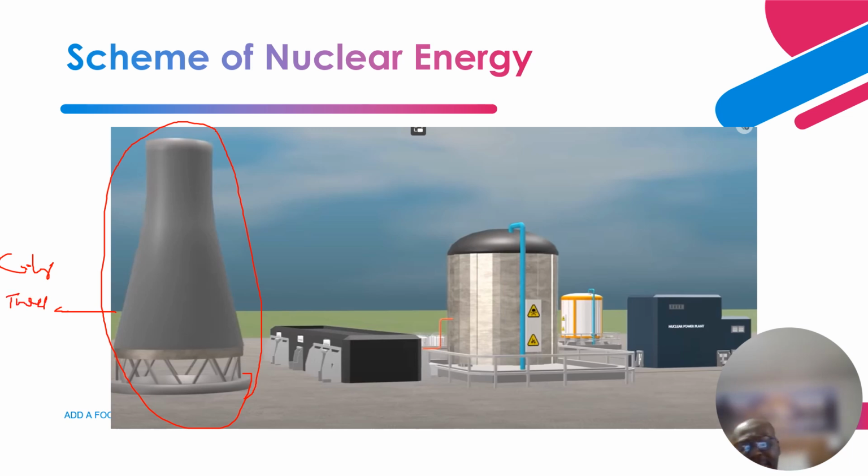This one acts like a heat exchanger, that allows the wasted coolant water that comes out of the condenser to be cooled utilizing river source water, and it returns back into the loop as a closed cycle loop. So this one is more of a heat exchanger.